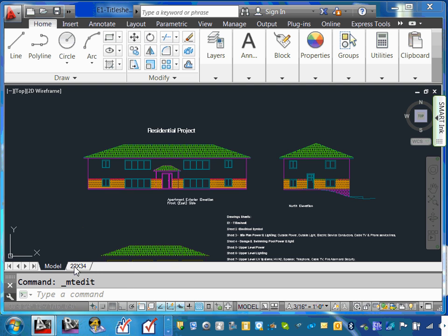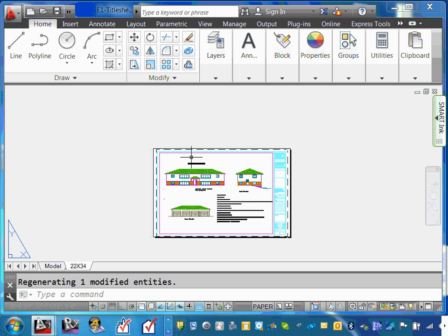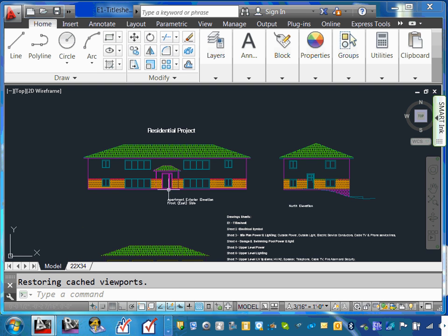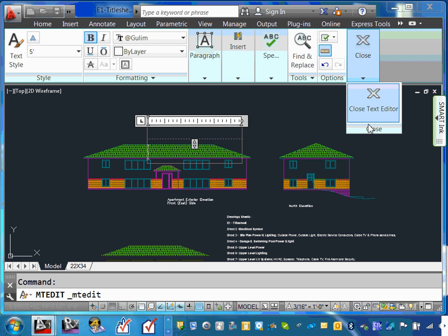Okay. So when you come to the print, it will look somewhere here, like a name of a project. I need it bigger than that, though. So you go back to the model space and let's do it again. Highlight it. I'm gonna put it actually probably like 5. Try 5. Enter. Is it big? Too big? I know you should probably have a standard for it, but for the time being, hit enter. Close that.